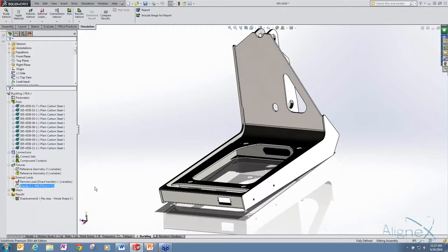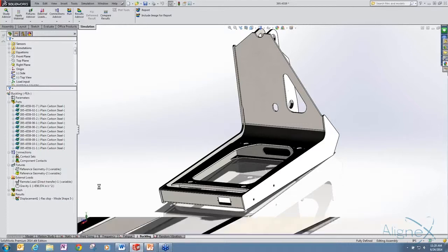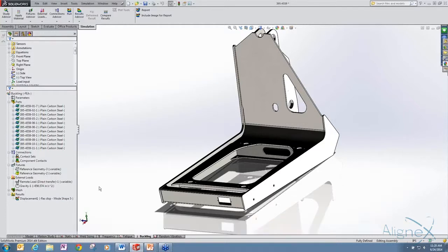Now, one important thing to talk about within SOLIDWORKS simulation is whenever we have different study types that we want to analyze, for example, I have a static study and then also a buckling study. What I can do is I can create the buckling study, and it will come in empty, and then I can simply just drag and drop these folders. So if I drag and drop to another study, you can see I can drop them into studies that they kind of qualify for. So I could drag and drop this to the static study or the weld sizing study. So that's what was done.